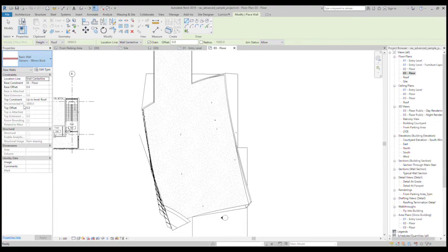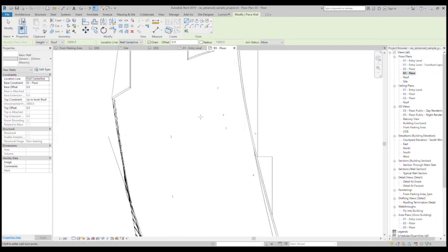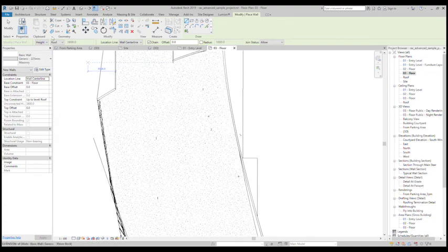Let's just draw a generic masonry wall. Okay. Now, walls work exactly like columns. It has a base constraint from what level you are drawing it from. There you guys can see. And it has a top constraint.